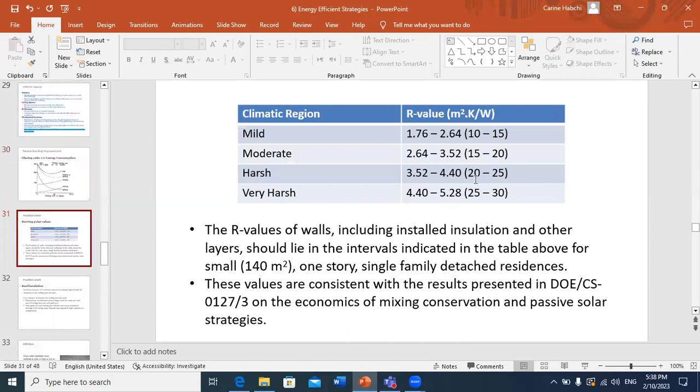So now here we have some recommendations, if you want, on the level of insulation resistance presented by the envelope in different countries. Of course, the recommendations will not be the same for different climates, because whenever you have a moderate climate, the difference in temperature between the inner and outer side will not be very large. So this will allow to go for lighter envelopes and lower insulation.